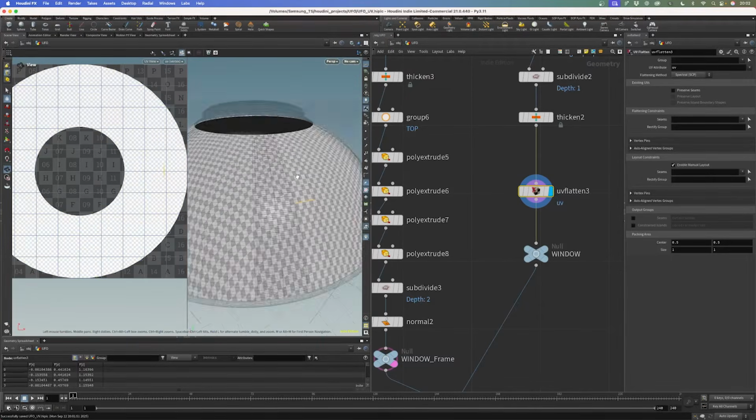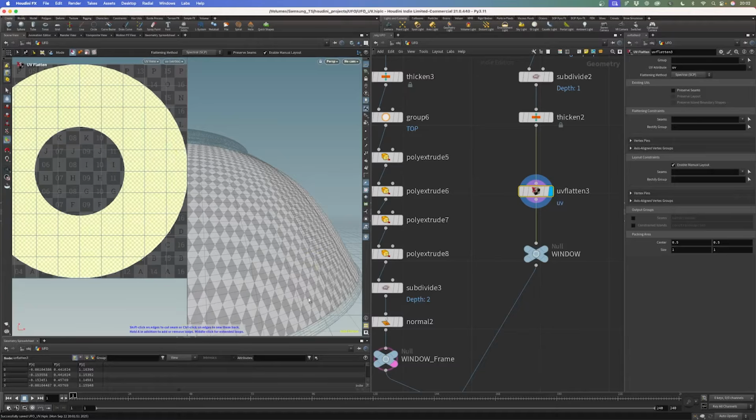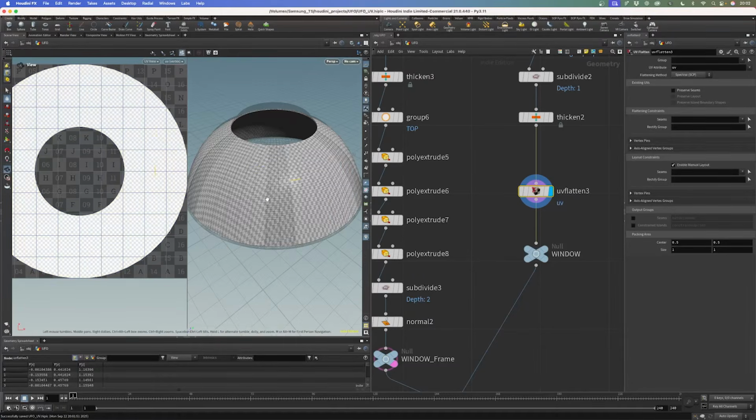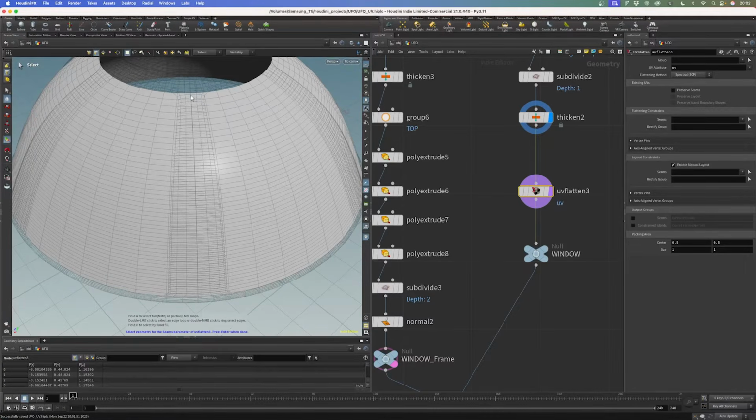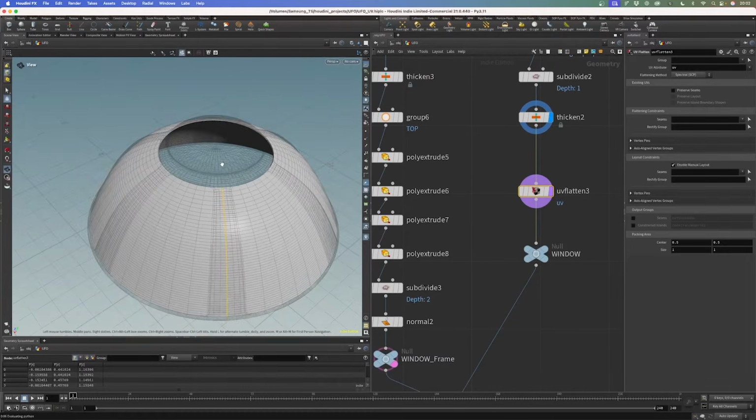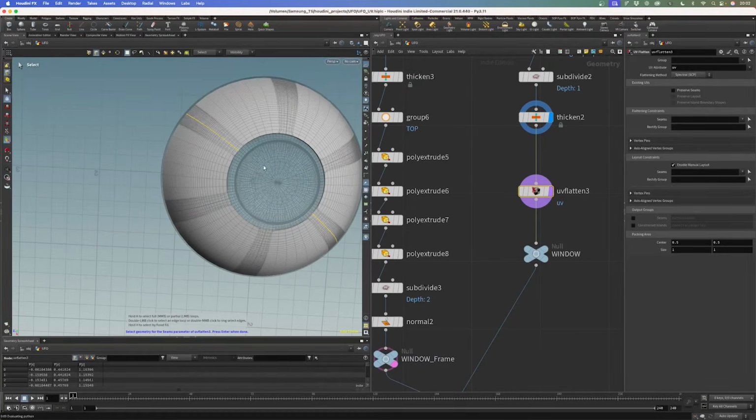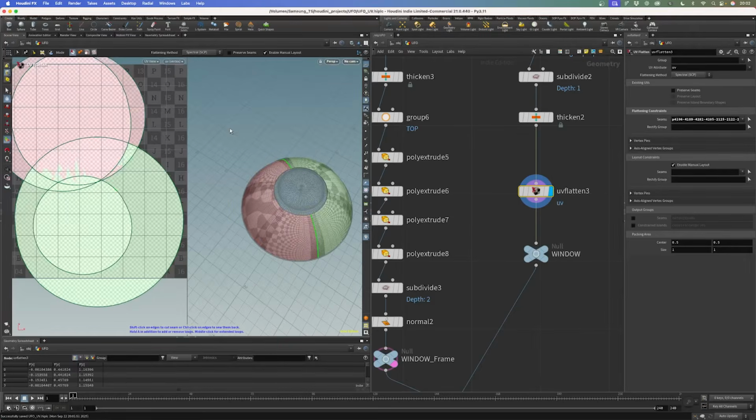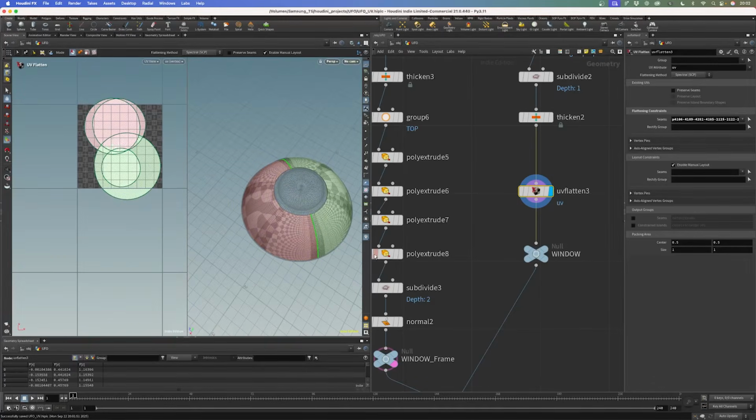It actually looks quite good, but we get a little bit of distortion here to the sides. So I would rather prefer to cut it open at one side to open it up, or maybe even split it up into two sides. So I can just double click to select the ring here and shift double click here to select the ring here. And we will get these areas.